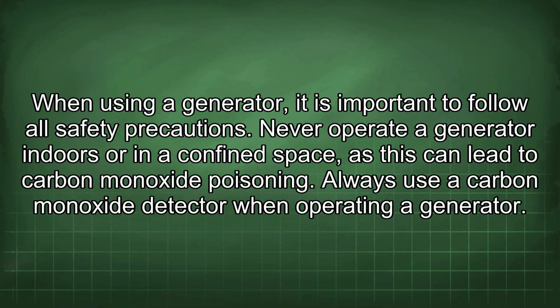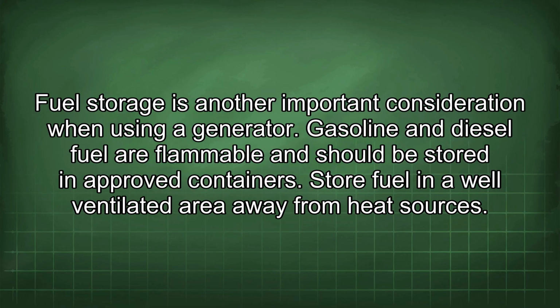When using a generator, it is important to follow all safety precautions. Never operate a generator indoors or in a confined space, as this can lead to carbon monoxide poisoning. Always use a carbon monoxide detector when operating a generator. Fuel storage is another important consideration when using a generator. Gasoline and diesel fuel are flammable and should be stored in approved containers.